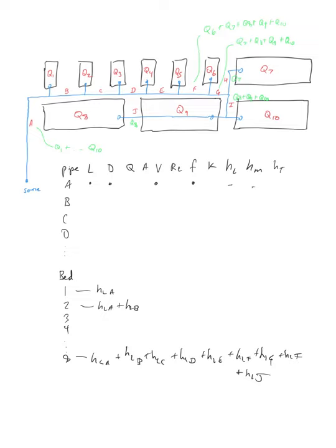And so what I want to do is ensure that the head I have available at my source, the beginning of the pipeline, is enough to overcome all of these head losses that I just calculated. If bed 8 is the most distant and therefore the highest head loss bed that I'm delivering to, do I have enough head to deliver that much water?